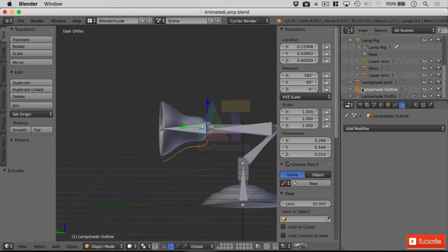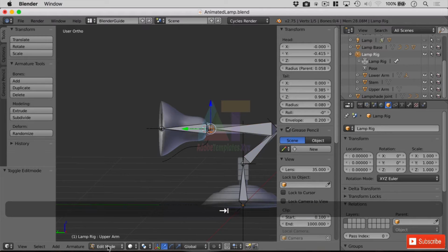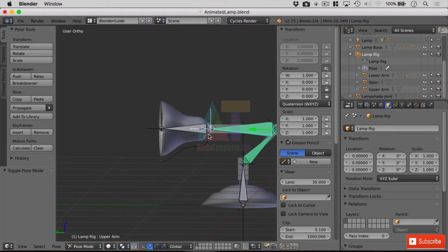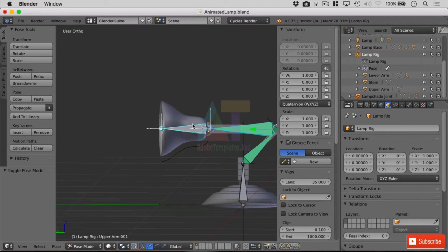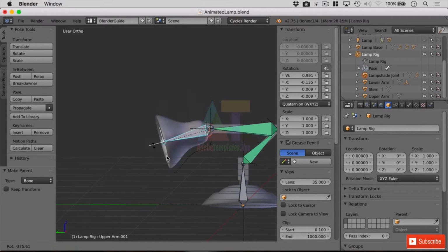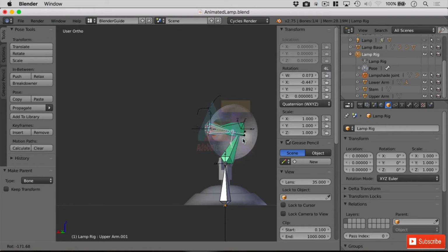I'm going to basically make the curves, I think, children of the joint, and then I can select the joint, select the armature. We do need to be in pose mode for this, so let's hop back over to the rig. Pose mode, excellent. So select the joint if I can, yep. Select the armature, or more specifically the bone that's connected, and then parent it. Control and P to the bone. Okay, so now we should see that that is constrained there, and if we move around we should be able to move it to the left, to the right, etc.